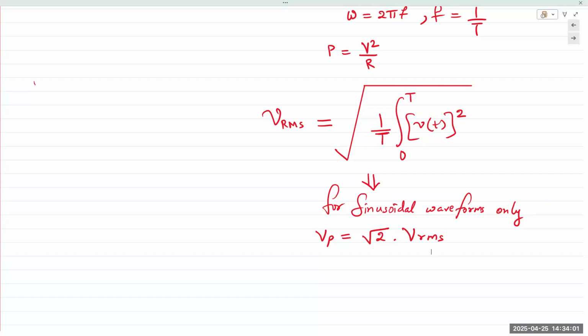In the lab, we use a function generator and we use an oscilloscope. The oscilloscope is the only instrument that we have used here that will display a waveform in peak to peak values. So power outlets, here in North America, elsewhere in the world, if there's a voltage getting specified, it's always talking about RMS values. It's not peak. So if you actually wanted to find the peak to peak value of the power outlet waveform, we would have to multiply by root 2 and then double that value.